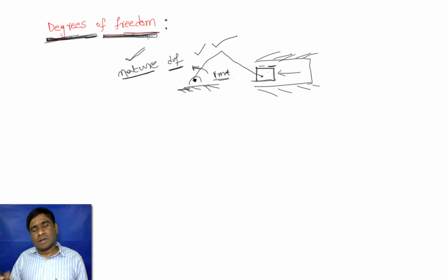In that case, generally people go for screw theory analysis, and they formulate some inverse and direct kinematics, and from that they segregate some matrices and then find the eigenvalues, and based on the eigenvalues they get to know the number of degrees of freedom as well as the nature of the degrees of freedom. Nature means whether the degree of freedom is a translational motion or a rotational motion.